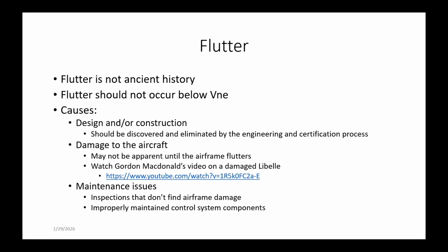It turned out that the aircraft had had a ground loop at some point, and one of the formers at the back of the aircraft, tying up into the vertical fin, had broken loose from the structure on the inside of the fuselage. What was really cute is I found out later, when I watched the video and was talking to a friend of mine in England, that it was his glider. Oh, how about that now?